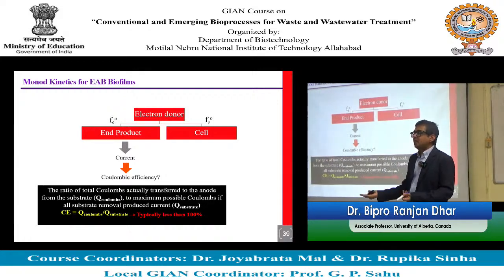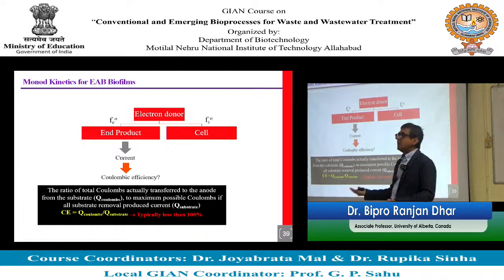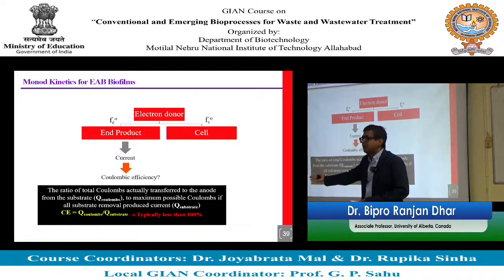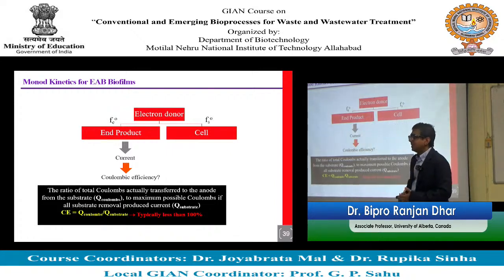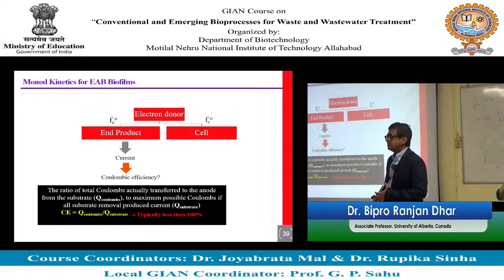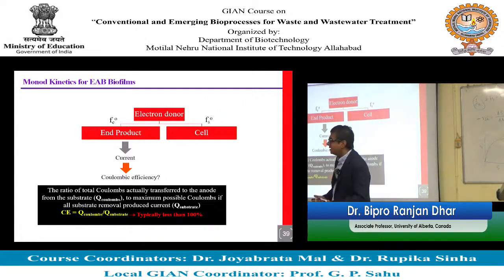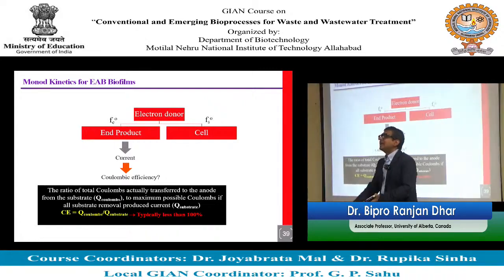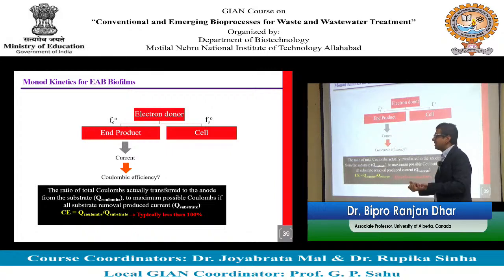Because with anaerobic microorganisms, or any kind of aerobic process, you are going to have more sludge production, right? So only a small portion, like 60%. It's not like efficiency, it's more like yield of current. But I don't want to use the term yield, because sometimes yield is used for how much biomass is produced. Yield is how much biomass produced per gram of COD removed, right? So we don't use the term yield.